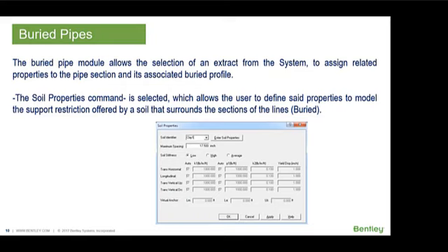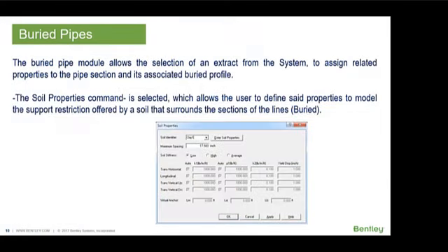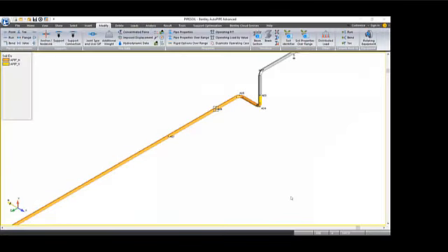That means you are adding a rigidity along the pipe, okay? That is very important because it's so different to have a model without soil and with soil. Of course, sounds logical. But imagine a line that we defined before, like this, okay, is in the air, suspended. So if we put soil, we have many springs supporting the line, okay? And that's the main idea of buried pipe. How it works a little, okay? This is an example already.